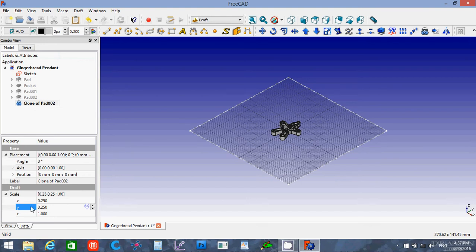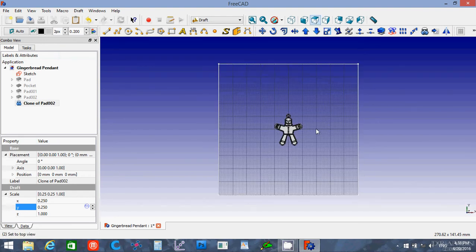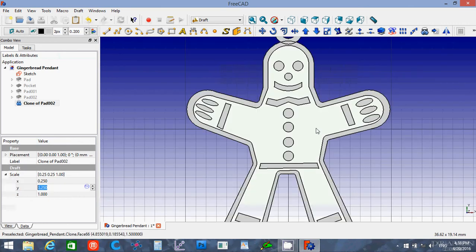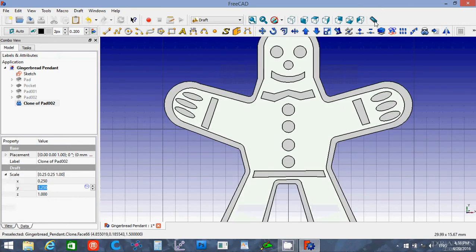And sometimes you gotta be alert to the fact that when you do this, my outer rim may no longer be 0.4 millimeters. If it's smaller than that, I'll have to maybe scale it back up some. To check that, I'll flip back to the top, zoom in, and what I like to do is just use the measurement tool over here.